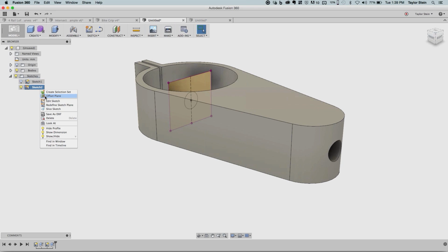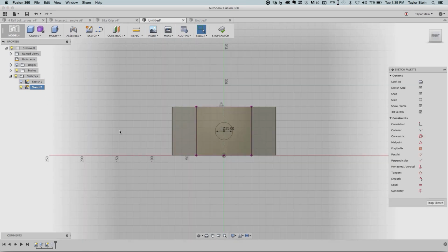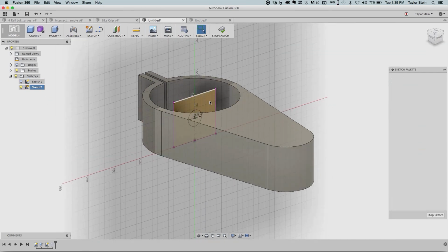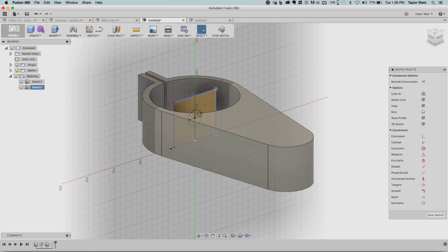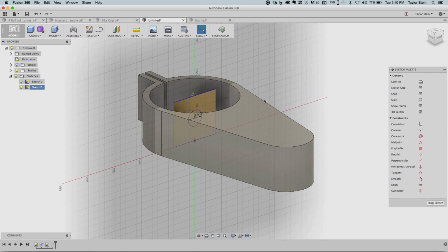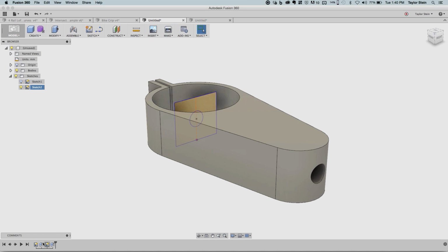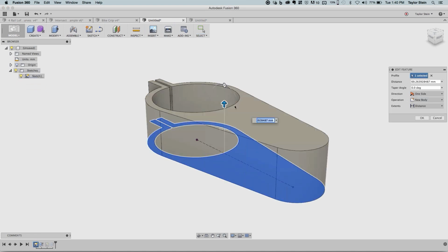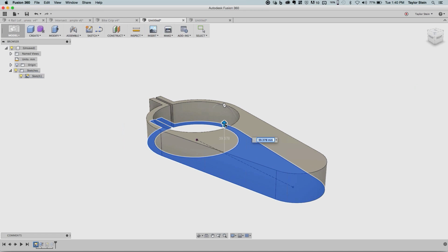So what you can do is in your sketch where you have that projection going on, you can select the curves. So I'm going to choose all this projected geometry, and you can right click and choose break link, and now it's just some underdefined geometry. So now if I were to go back and change this extrusion, you'll see that that projection does not update.